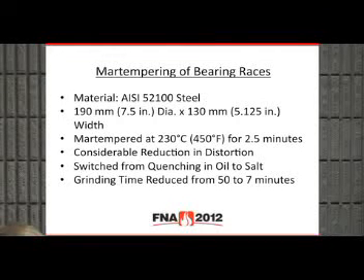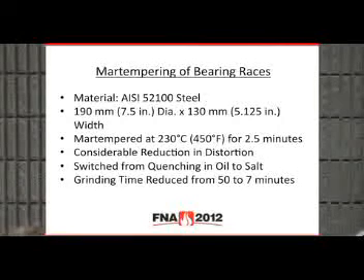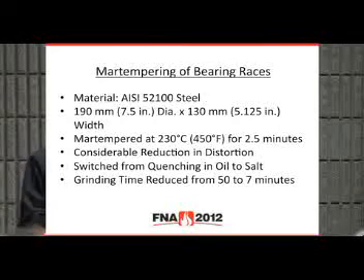As an example, martempering of bearing races: I have given one example here where martempering is carried out at 450 degrees F for 2.5 minutes, and there was a considerable reduction in distortion. In this particular case, the customer switched from oil to salt, and he was able to reduce the grinding time needed for corrective sizing from 50 minutes to 7 minutes. So that gives you a magnitude of how much distortion has decreased.